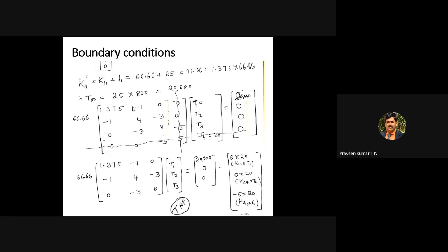So originally, even in a finite element package, the original value is saved in the system. Then at a later stage there is an updation of the thermal conductivity values. That's the one part. Then on the right hand side, we have R1 plus h into T infinity. R1 is 0. The h value is 25, in terms of meter only, and T infinity is 800.